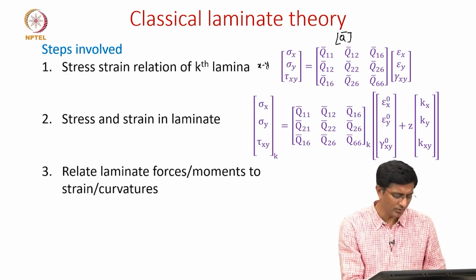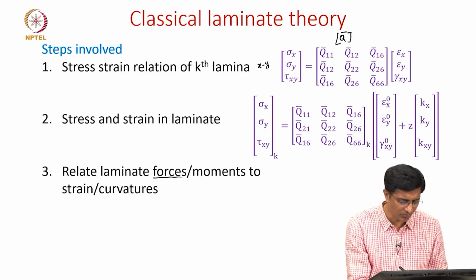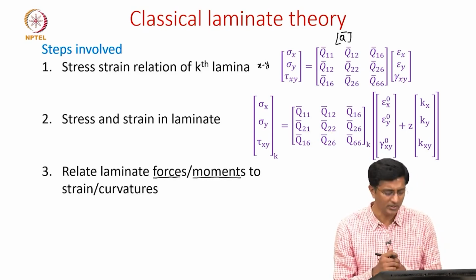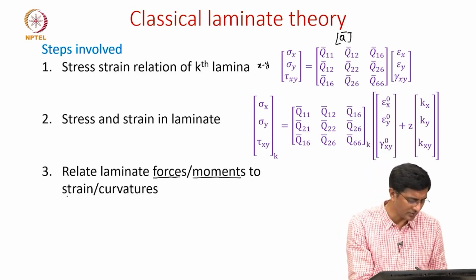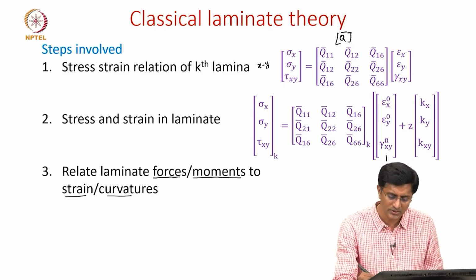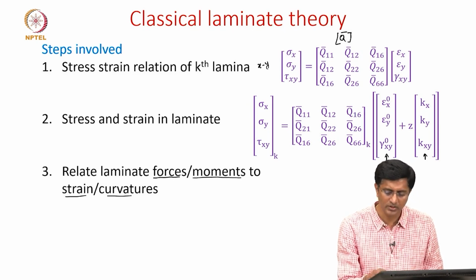So in this video, we will be focusing on the last step, where we now start to discuss what are the forces and moments applied on this laminate. We will write these in terms of the strains and curvatures which we have shown here. So these are the mid-plane strains and these are the curvatures. So we will try to write these forces and moments in terms of the strains and curvatures.